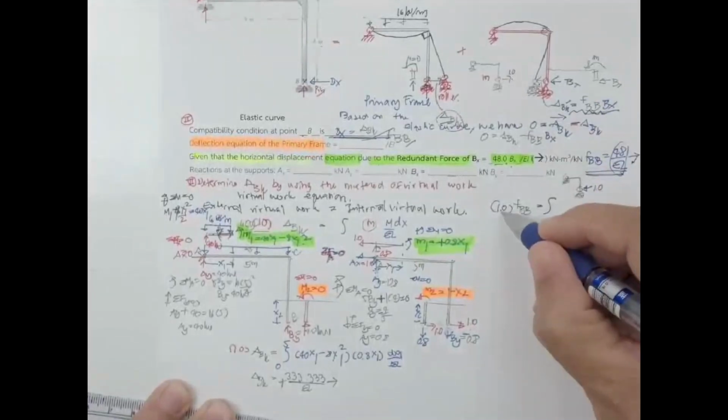We're going to have the frame also. Okay, our frame is now subjected to a 1.0 force in this direction, in order to provide this kind of displacement. And then due to the 1.0 unit load, we have this one for M. Okay.